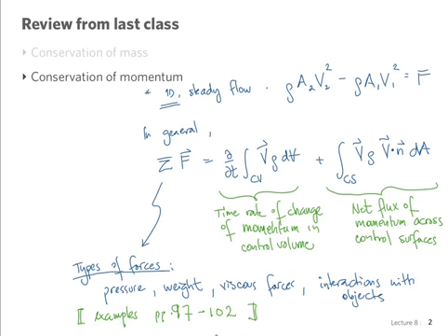And the strength of that analysis system is that everything that happens inside the control volume that we've decided to use for the analysis is completely a black box. You don't care what's happening inside. What you care is what comes in, what comes out, and you use this analysis to determine any forces that are applied to this control volume using change of momentum.